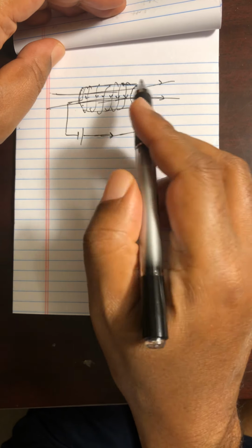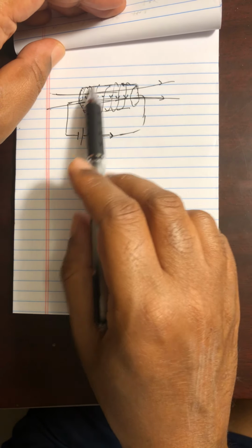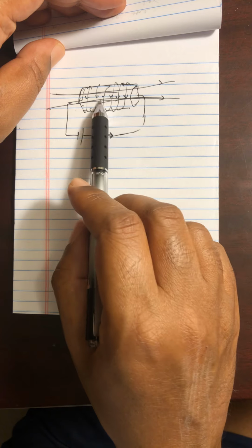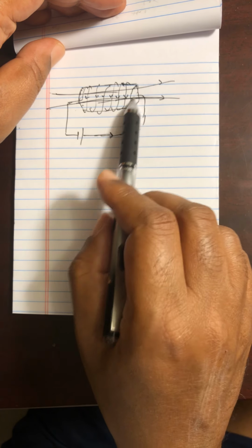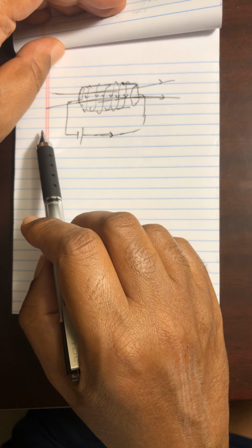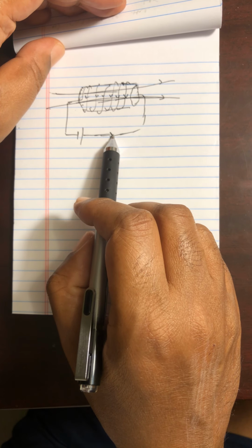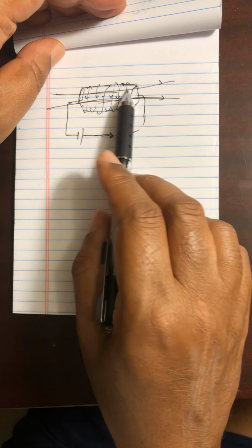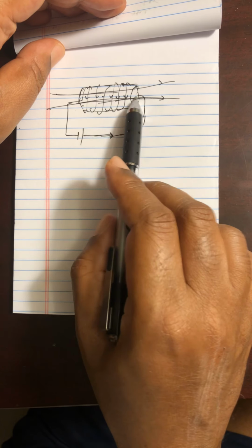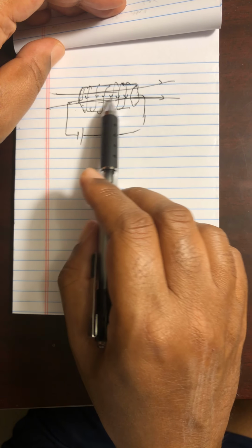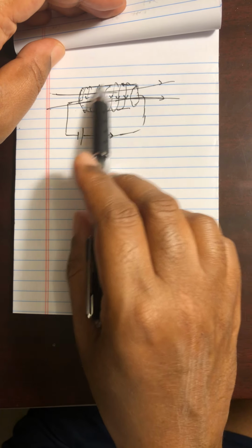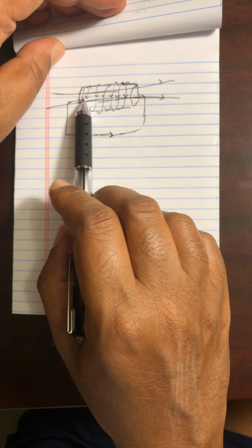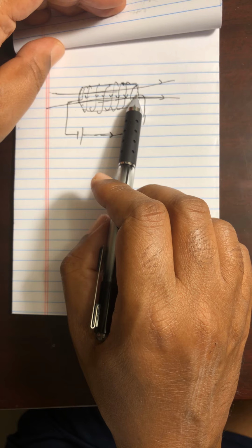Okay, now you see this coil over here is being crossed by its own magnetic field, so it has magnetic flux because of its own field. Now if we change the current over here, the field over here changes, so there will be a change in flux crossing this solenoid because of its own field, and that change in flux will produce induced voltage in the solenoid. Now since this induced voltage is produced by its own current, it's called self-induced voltage.